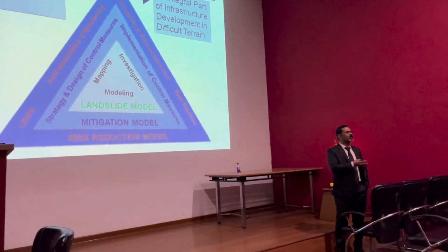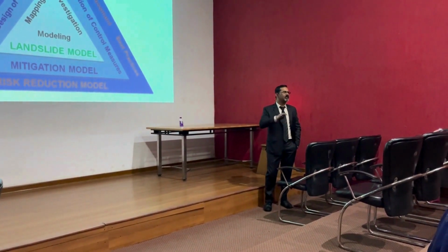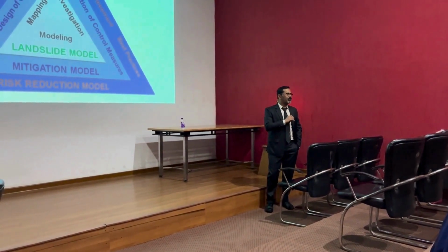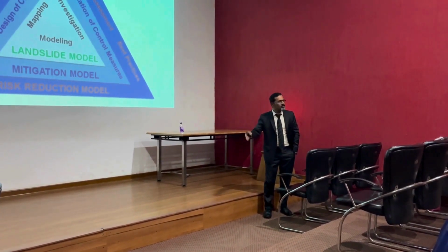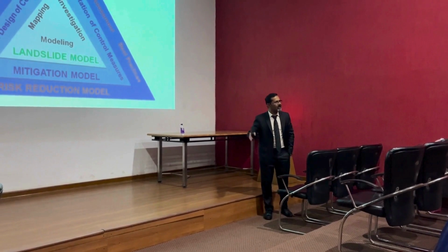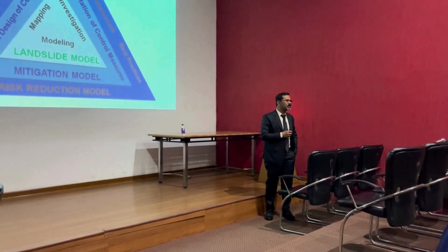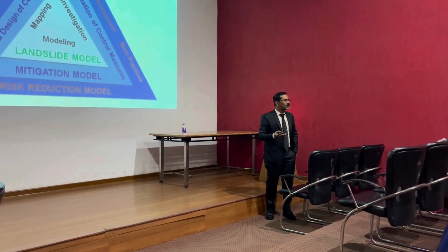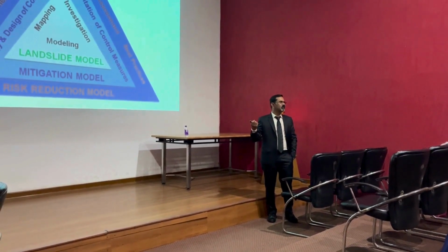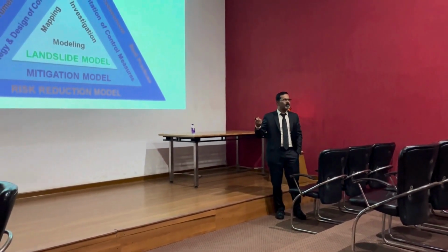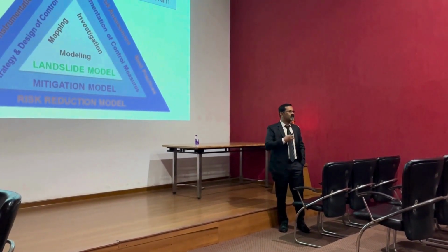What is the requirement of Bureau Standards code? That whatever you design, you have to design at a factor of safety of 1.5. So if it is a hill slope, there is no toe support, you will first design a retaining wall. Put that retaining wall in your numerical modeling and see how it is improving. Still, there is some problem, you have to put some drainage pipes. You take out the water pressure. If the stress due to water pressure is reduced, again your factor of safety increases.